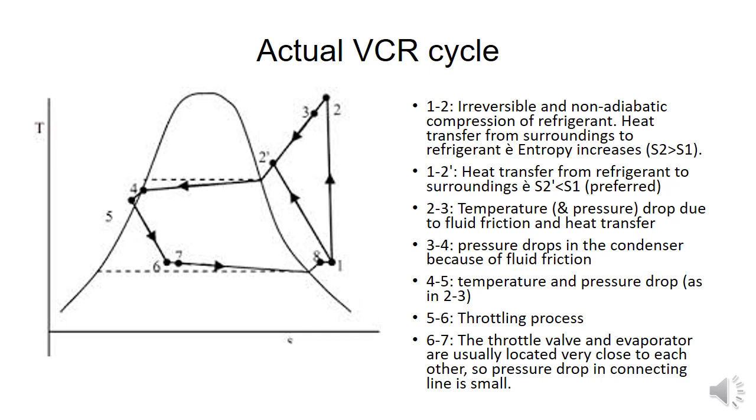So the compression part is mostly above the saturation line, therefore superheated vapor is generally used at the inlet and outlet of the compressor. Similarly, the subcooled zone is very small, between 4 to 5, therefore less subcooling is part of the standard actual vapor cycle. And we have seen that in isothermal condensation and evaporation, actually there is a slight temperature variation when pressure falls and temperature increases.